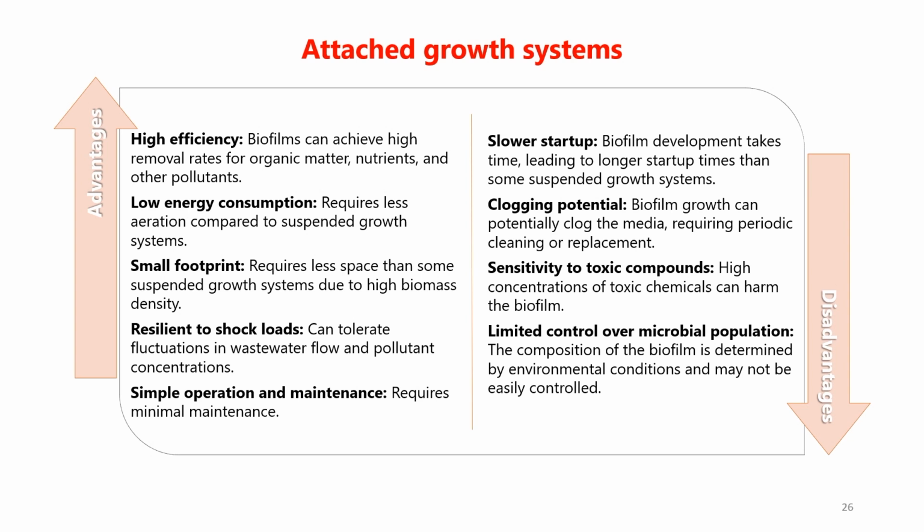Again, like any other system, they also have certain disadvantages. For example, they have a slower startup. Biofilm development takes time. Until the microorganisms are arranged and encased in an extracellular matrix to form a biofilm, they won't be able to show their metabolic activity as a group. So, this leads to longer startup times than some suspended growth systems where degradation may start quite early.